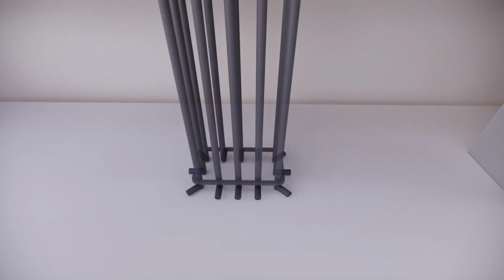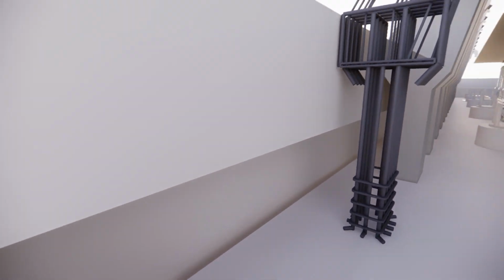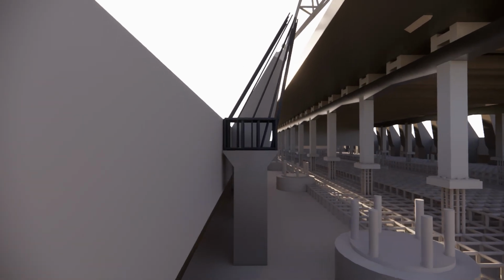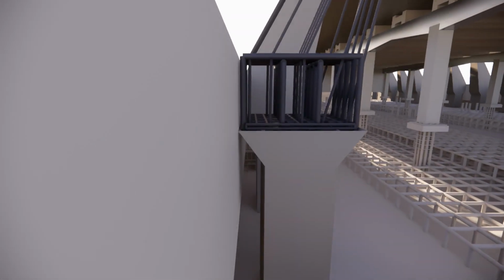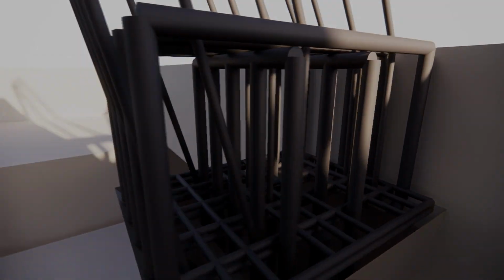Just like any typical structure, the construction of the roof part's foundation begins with the most fundamental element of the building, the rebar. We erected reinforcing bars to support the structure and surrounded them with rebar rings for additional stability. The top of the pier is shaped into a trapezoidal form known as coping. This coping effectively transfers the load applied over a wide area to the column beneath it. Do you see the reinforcing bars protruding above the reinforced concrete? These are intended to form a connection with the support base, which I will explain next.